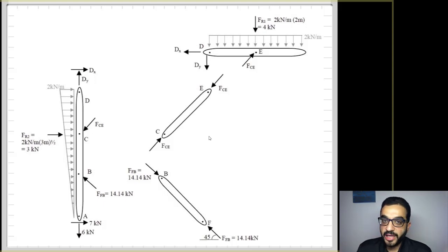So I have a hinge joint D, so I'm representing DY and DX because it's a hinge. And before I do that, I recognize here that members ABCD and DE are not two-force members. They are multi-force members. So when multi-force members are connected, multi to multi, I can't simplify anything. It's a hinge support, represented by 2 reactions. But when I represent it as 2 reactions, DY and DX, in one hinge, on one free body diagram, I reverse the directions on the other member.